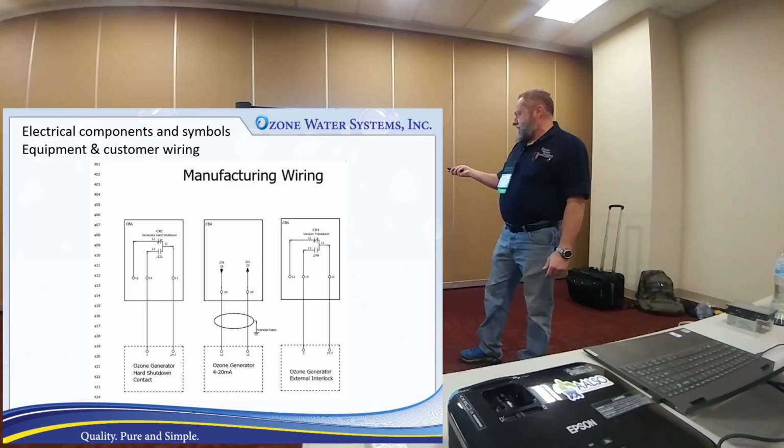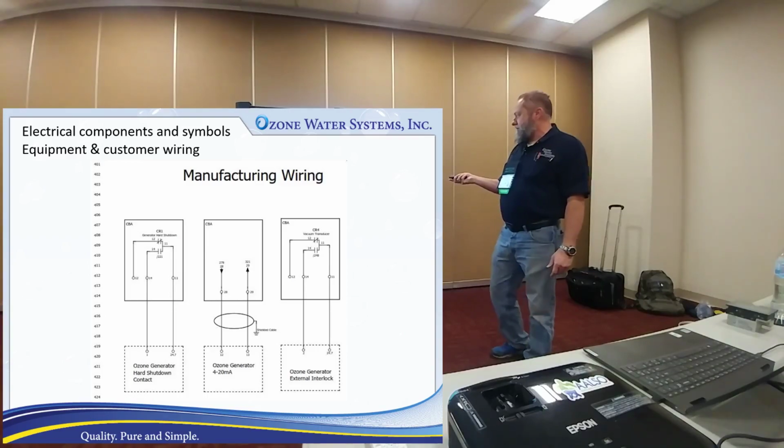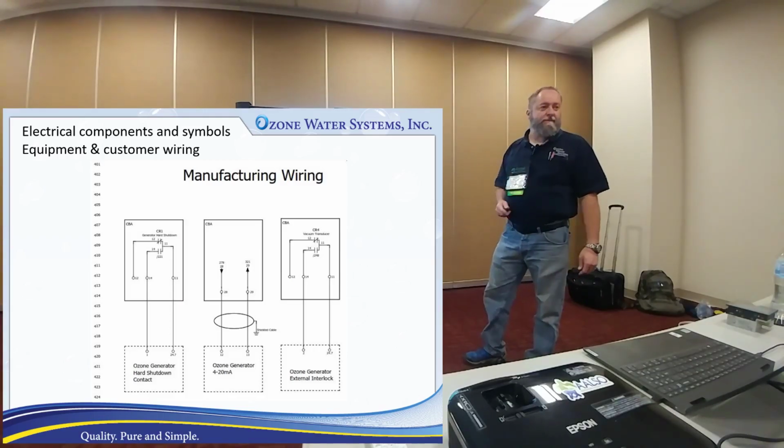You can see your control relays there. You can see how we've used those. We're using the normally open on that one, normally open on that one. This one happens to be an analog signal coming out of that splitter. So actually comes out of the splitter, goes out to the generator, and it comes back, and then it goes over to that telemetry unit.